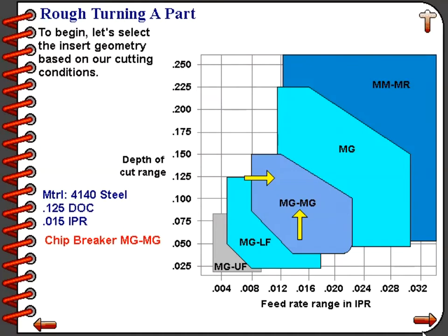The feed rate at 15 thousandths per revolution is a fairly good starting point for a roughing feed rate. However, from an efficiency point of view and an optimization for tool life, you want to increase your depth of cut and then increase your feed rate secondarily. And that's how you would optimize this cycle down on the machine.